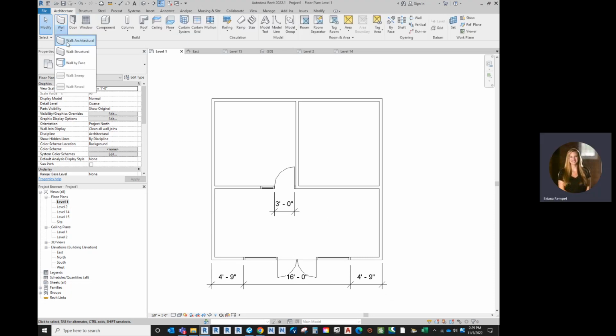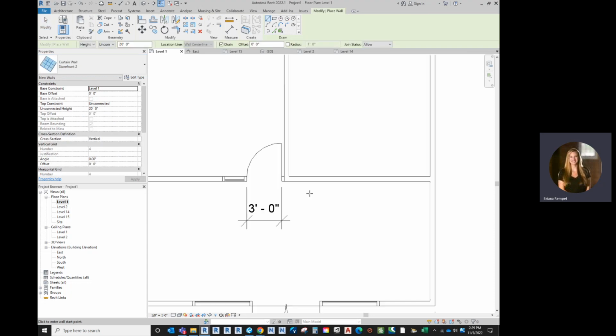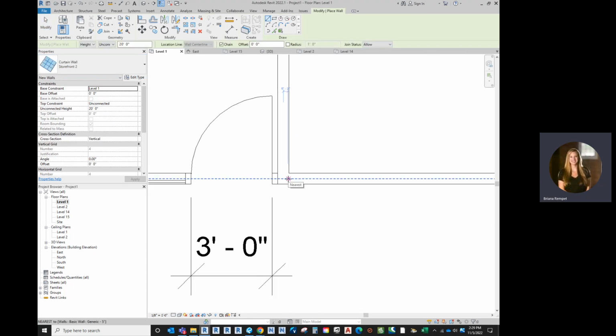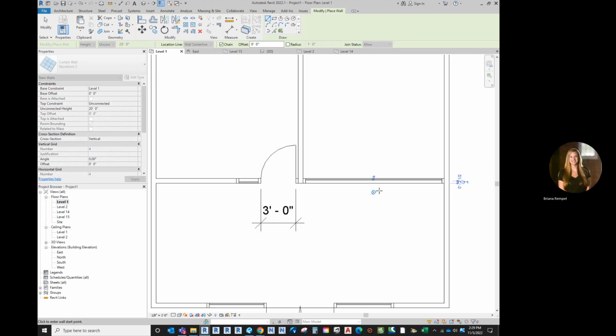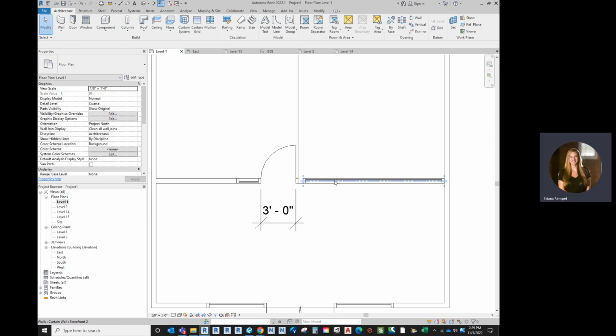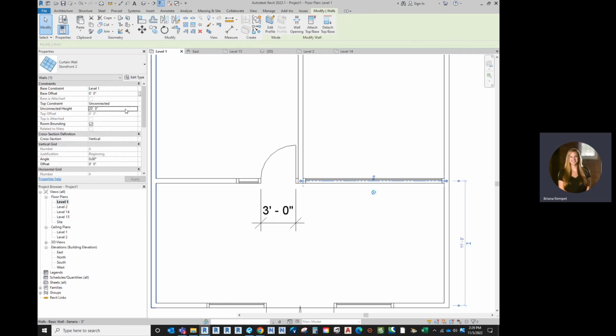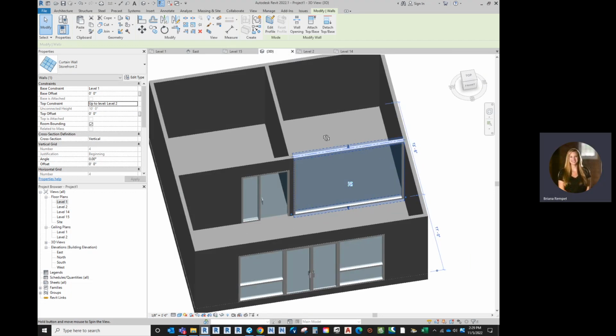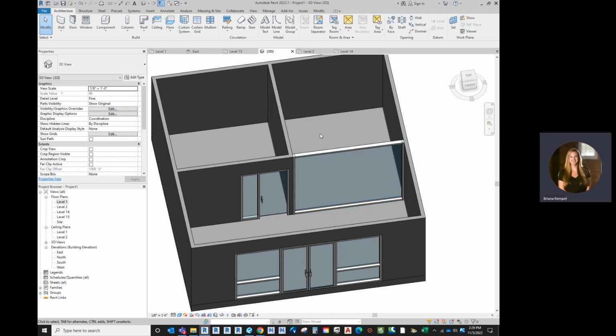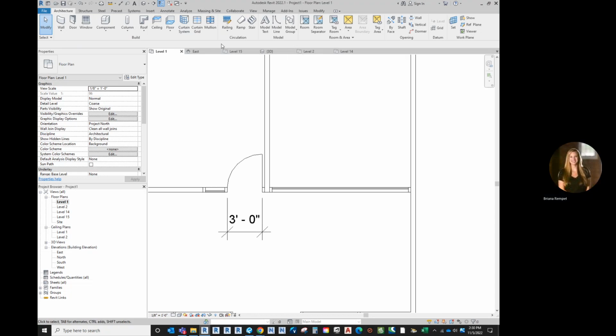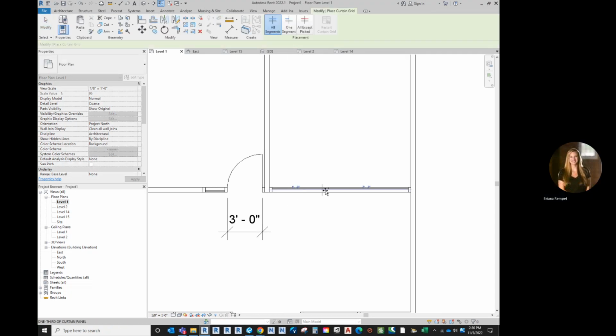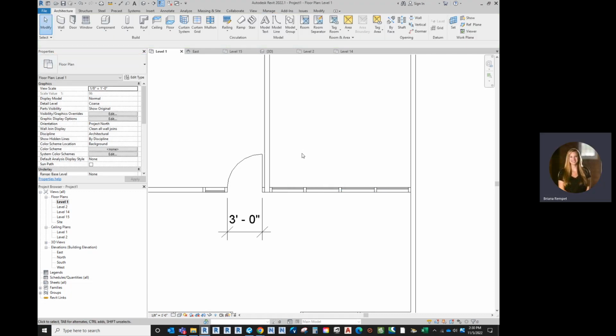All right, now let's take a look as if we were going to use it for an interior demountable partition. I'm just gonna go across the room there. It's still going to be at that unconnected 20. I'm just going to go ahead and put this one up to level 2 as if it was the entire wall here. And then I can go ahead and add in grids. Again, you can do that in floor plan or 3D. Also, if you start in the middle like that, Revit kind of helps you default to equals in between the panel sizes. All right, so now I have my vertical grids.